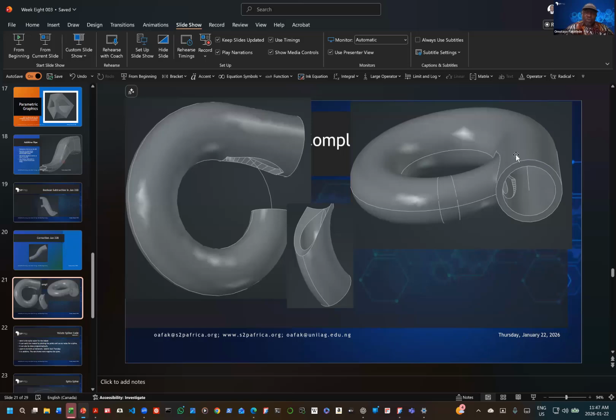When you try to do a loft or a sweep that enters itself, FreeCAD goes mad, it goes crazy, and it does all sorts of funny things. So the solution to that is that you do it in 2 steps. You do it in such a way that it doesn't enter itself. And then you come and do this other part. Getting this edge is very complicated.